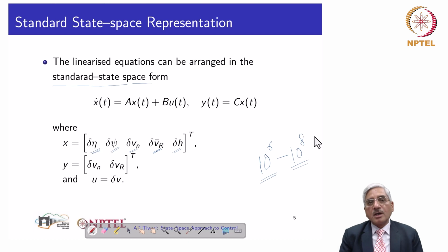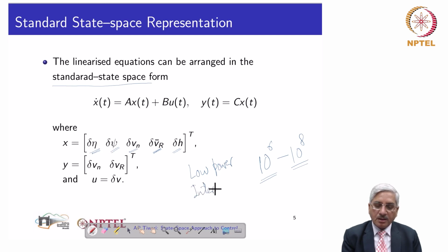So it means that the neutron flux density measurement has to be carried over about 8 decades or minimum 6 decades. This is an enormous range, and this enormous range is not possible to manage by a single set of instrumentation and amplifier. So for measurement of neutron density in a nuclear reactor, we have low power measurement or logarithmic range measurement, we have intermediate power or intermediate range measurement, and we have normal power measurement.